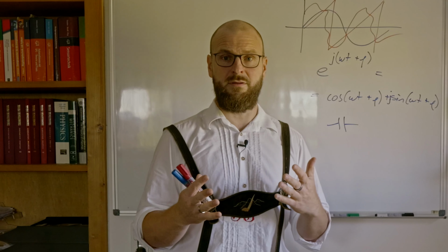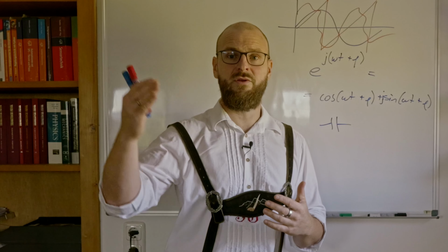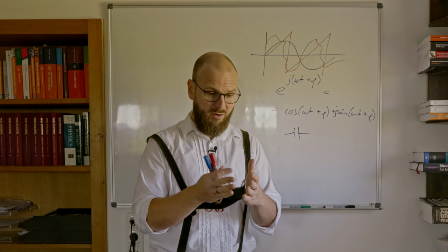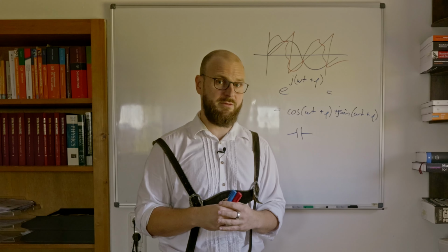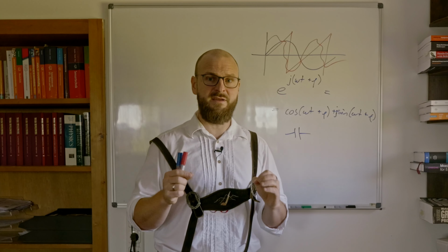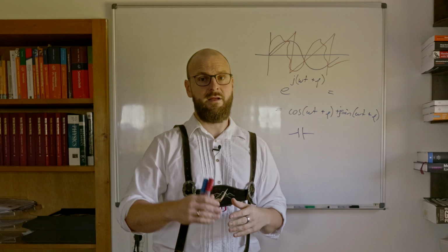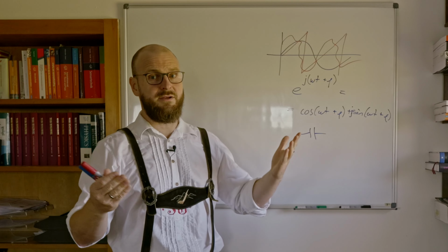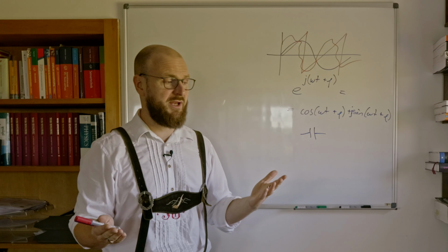When we are not able to talk about that arbitrary function as it is, we are able to do a Fourier transformation, meaning to get all those sums, to get all the frequency parts of our arbitrary signal, and then we are very directly, very specifically able to talk about the behavior of that arbitrary signal. Meaning, if there's a sharp edge, high frequencies occur, and those high frequencies might be cut due to some capacitance or something like that.